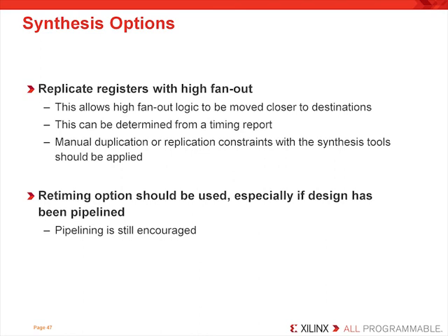When you duplicate logic, don't forget to also name this duplicate logic appropriately. Specifically, use the same name followed by an underscore A or B. This will prevent the tools from seeing the logic as related as in a bus. By default, synthesis tools tend to duplicate logic and give it a number as in underscore 1 or underscore 2, and this forces the logic to be related and directs the implementation tools to keep it placed close together. So rename it A or B as I described.